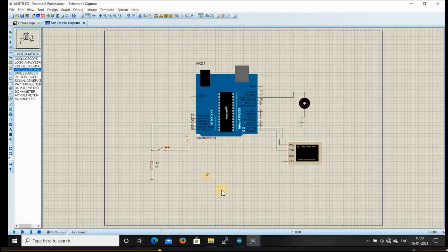Now let us discuss two cases here. In the first case, we are going to fix 20 seconds as the time limit in our controller. I have given the power supply to the Arduino and to the motor through the controller. If we switch on the power supply, then the controller passes the signal to the motor through the 11th pin for only 20 seconds. If the time limit is exceeded, the motor automatically turns off, because even though the power supply is on, the controller doesn't pass the signal to the motor through the 11th pin.